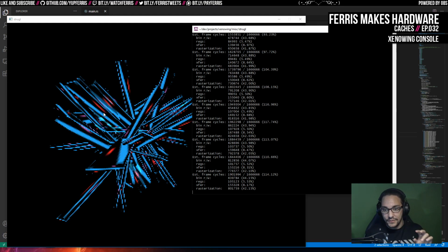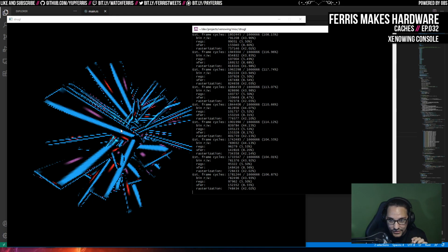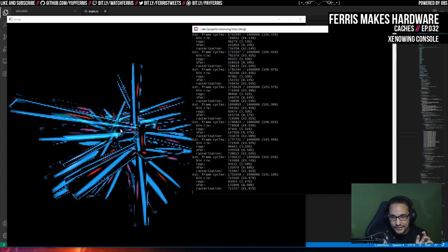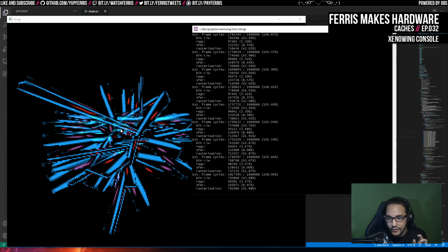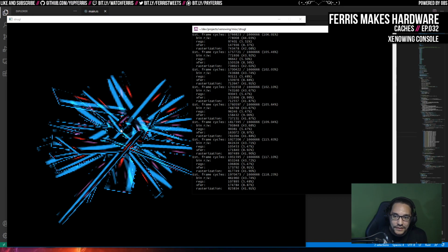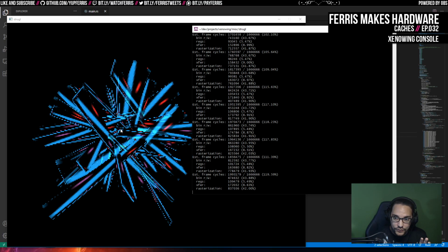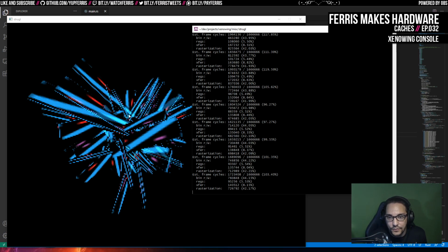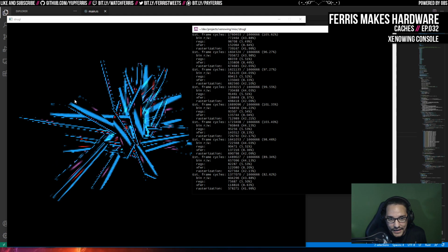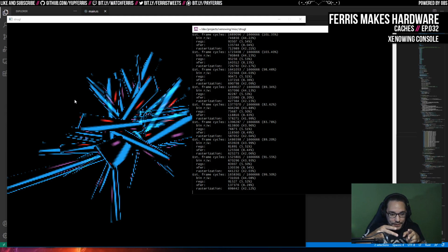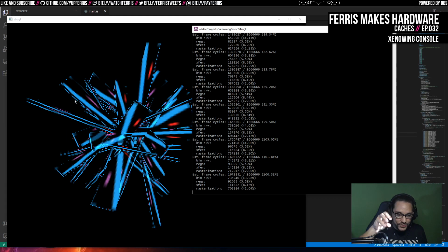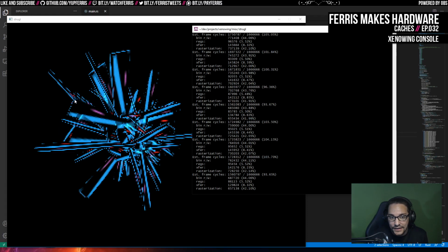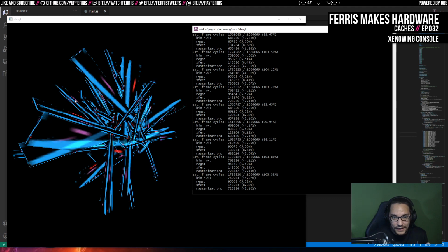Or actually, before I move on, there was another reason I want to do the texture cache that way. Or maybe not the texture cache in particular, but another change I need to make: if you want to do mip mapping, you need to render at least 4 pixels at a time. You usually do that in a 2x2 grid. So within the tile, instead of 1 pixel at a time through a pipeline, you would have 4 parallel pipes, and then you pass little blocks of 2x2 pixels into those pipes. So first of all, that should accelerate things because it'll have more pixel pipes.